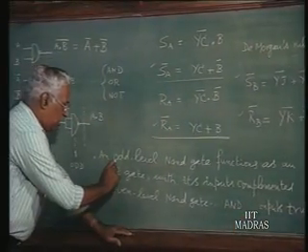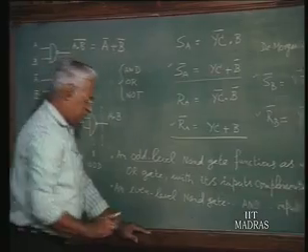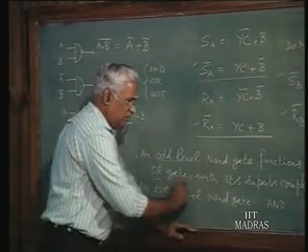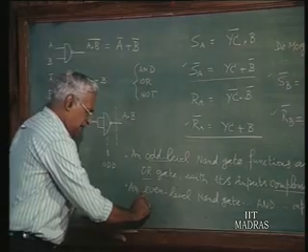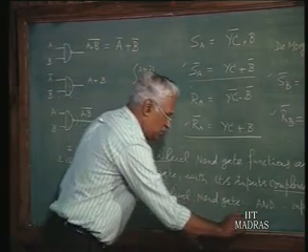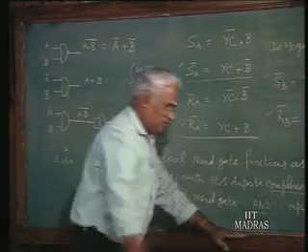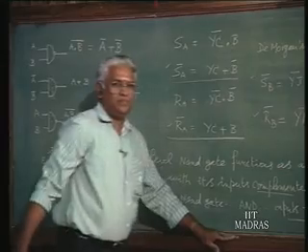That is, an odd level NAND gate works as an OR gate with its inputs complemented. An even level NAND gate works like an AND gate with its inputs true.